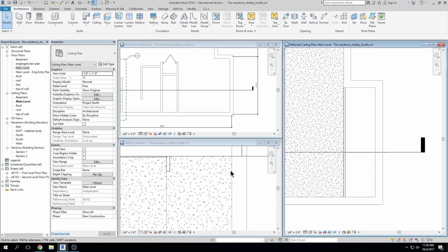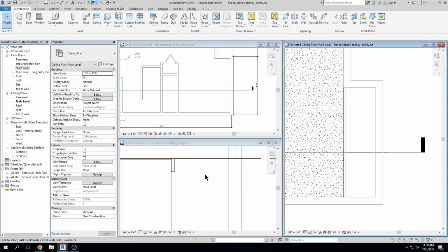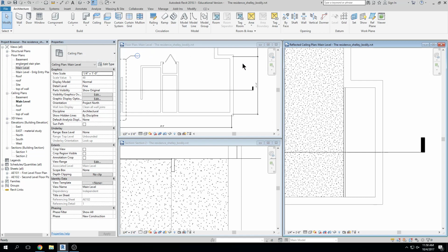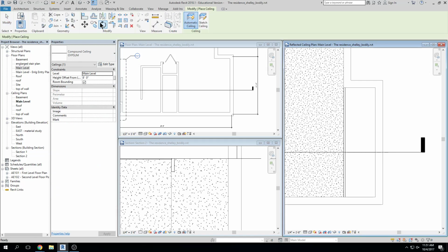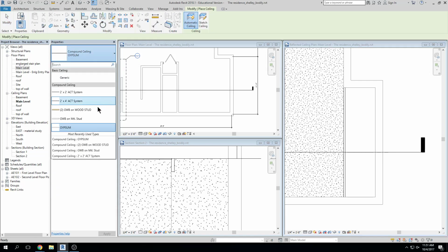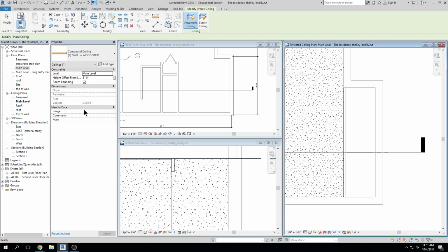and go over to here, right? So now I need to create a ceiling here for this little soffitted area that is dropped down. Okay, it's just a lower level ceiling. Still in my RCP here, I'm going to choose the type of ceiling that I want to create. Let's see, ceiling. This one, I'll choose gypsum board on wood stud, 2 layers.